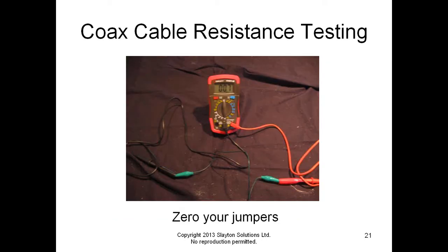Now, the other thing that you need to know is the resistance of the cable. To do this, we need a multimeter or a volt-ohm meter, the common meter that alarm technicians use. This one right here is a Triplett meter. It's not very expensive. Everybody should have an electrical meter. But what you're going to do is take your meter and set it up to read resistance, to read ohms, because that's what we're looking for.